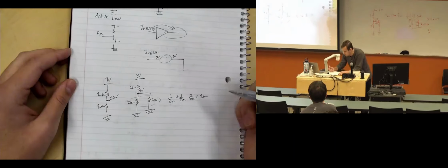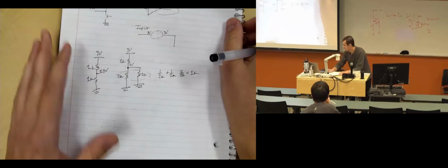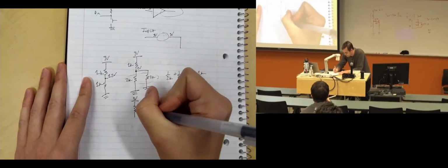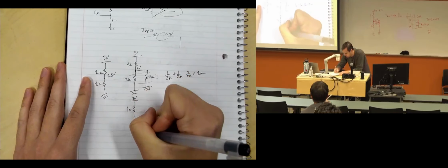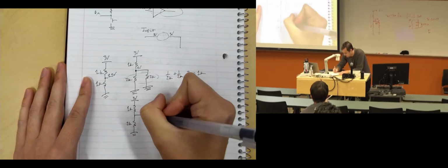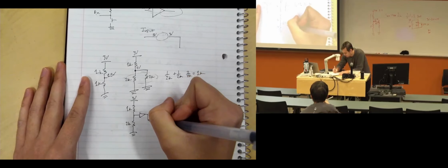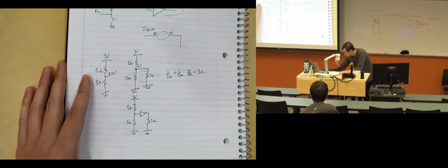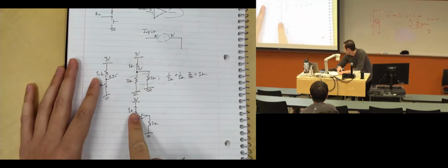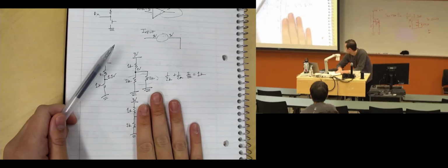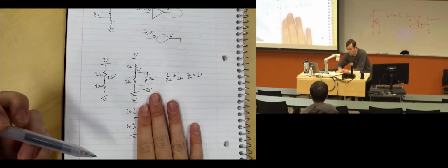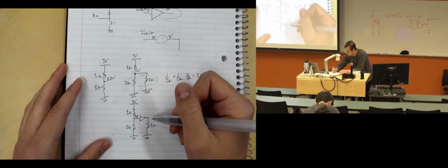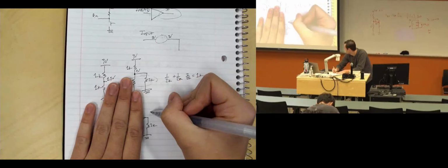We wanted 2 volts. So what you can do is take this entire circuit, same exact thing, 3 volts, resistor divider, 1K, 2K, and put an output buffer here, then the 2K. What's going to happen is this side of the circuit looks just as we had it before, what we expect. It's going to put 2 volts here, and to this side of the circuit, it looks like this isn't here, and that there's 2 volts.